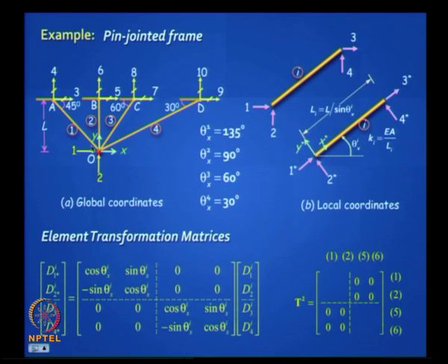So if you take, for example, this element 2, we want to fill here and here, but we can straight away mark the linking global coordinates. See, we have identified this element is 1 2 and it is matching with this 1 2, and this is 3 4, but for the global coordinates this is not 3 4, this is 5 6. Are you getting what I am saying?